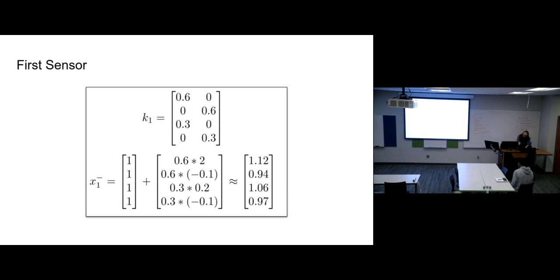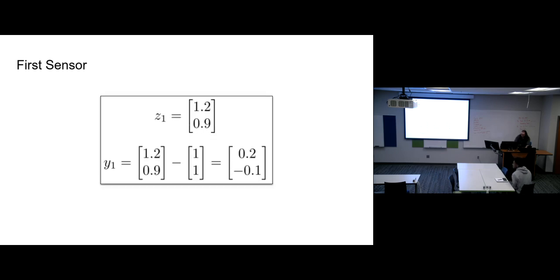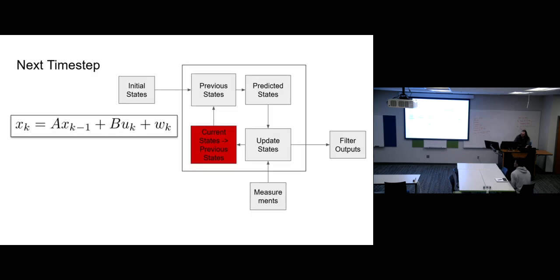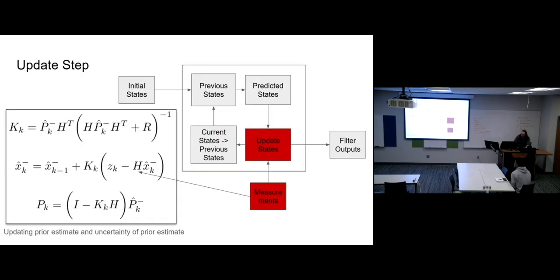Say if you're getting closer in range to something, or it's getting closer to you, the covariance matrix, the error bounds can actually decrease and weight that data higher. And that's what you see here: the Kalman gain gets updated every recursion with its current measurements, its current predictions, the process noise, all of that. So it is a dynamically changing process. It's very organic in that way.